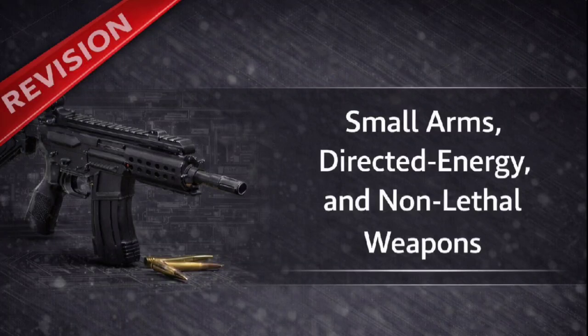Let's detail some of the specific engineering features that highlight its modern design. Well, the manufacturing process prioritized cost and speed. The weapon's main housing body is constructed from pressed sheet metal rather than expensive machined steel. And that's possible because of the locking system. It's viable because the stress of firing is minimized on the body itself. It uses a front locking system, a rotating block breech with 2 lugs that engage a heavy barrel extension. This means the primary stresses are absorbed by the barrel assembly, not the housing.